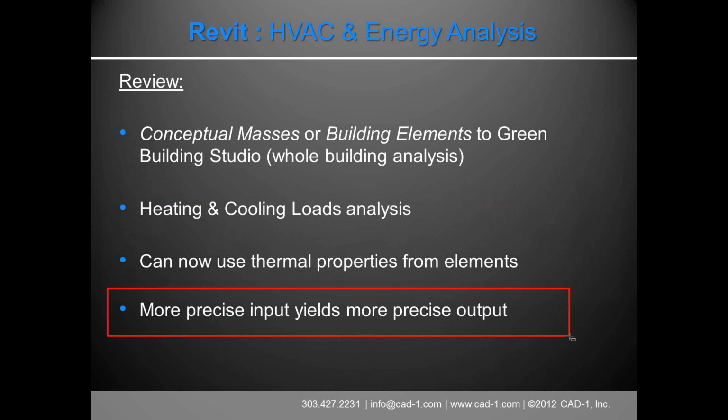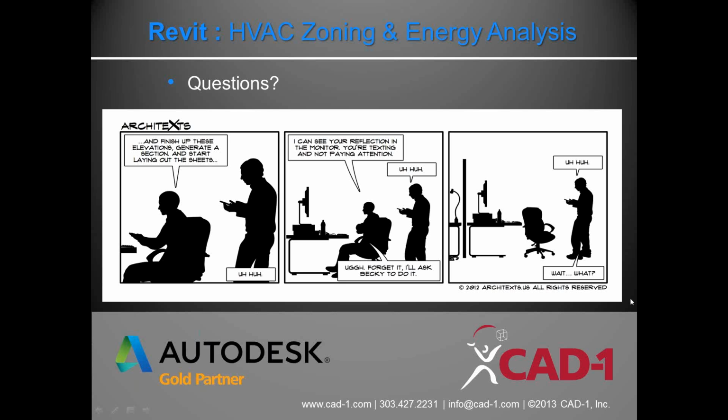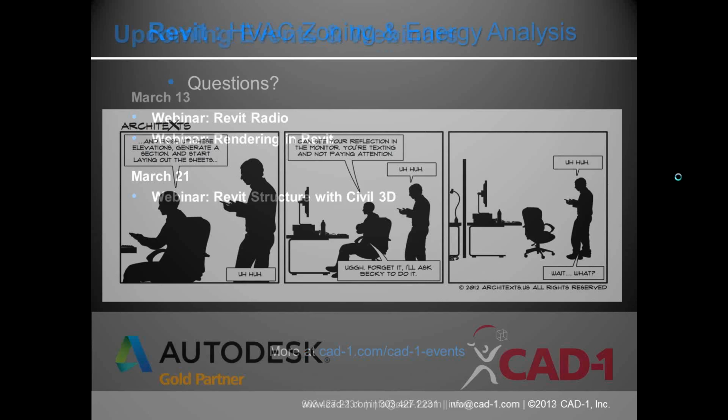I know I've heard of companies say, we tried the analysis in Revit. It was horrible. It wasn't accurate. I'm like, well, how much time did you spend? Well, we just hit analyze. Well, of course it was wrong. It just had default values, which is software sold around the world. It's not going to know your building, your location, your building service. But with that said, there is also the factor that the earlier in the modeling process that you start to do this analysis,